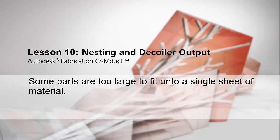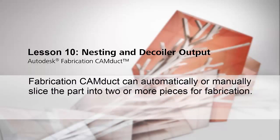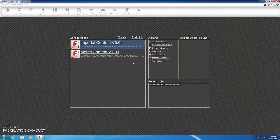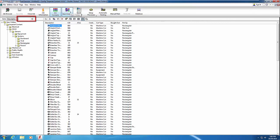Some parts are too large to fit onto a single sheet of material. Fabrication CAMduct can automatically or manually slice the part into 2 or more pieces for fabrication. Create a blank job. Select Item Folders from the utility bar. In the search field above the Folders pane, type Transition and click the Search Now button.